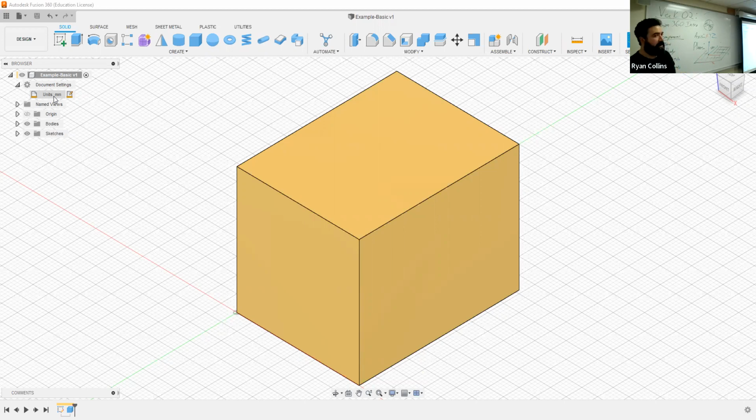that reference guide. But most 3D printers, as well as the intermediary software that takes your 3-dimensional model and preps them for 3D printers, usually called slicer programs, we're going to do it later. Most of that default language for those is millimeters. Often I run into it when I build something in inches, there's often a scaling issue. So not that if I built this in inches and changed it to millimeters, it'll stay the exact same size. It'll just be a different